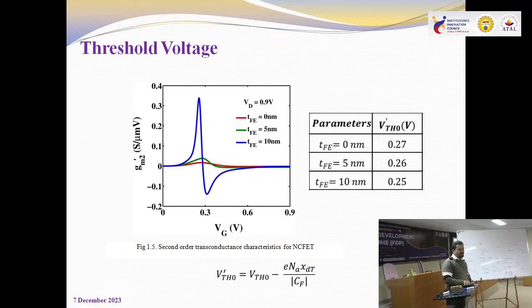Whenever things go to the fab lab, standard values are there and you have to stick to those values. You cannot bypass those rules. So the dielectric thickness is fixed, and its permittivity is also fixed. If you take SiO2, it's 3.9. If you take hafnium, it's more than 3.9, in the range of 20 to 25.